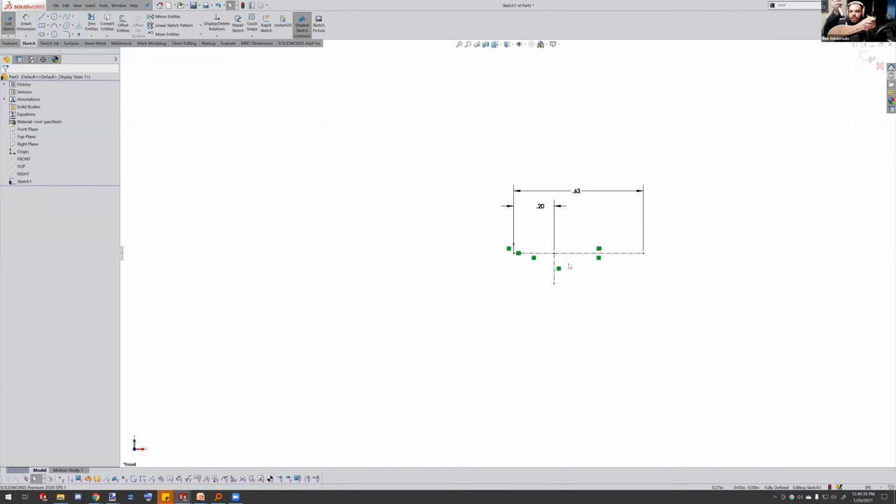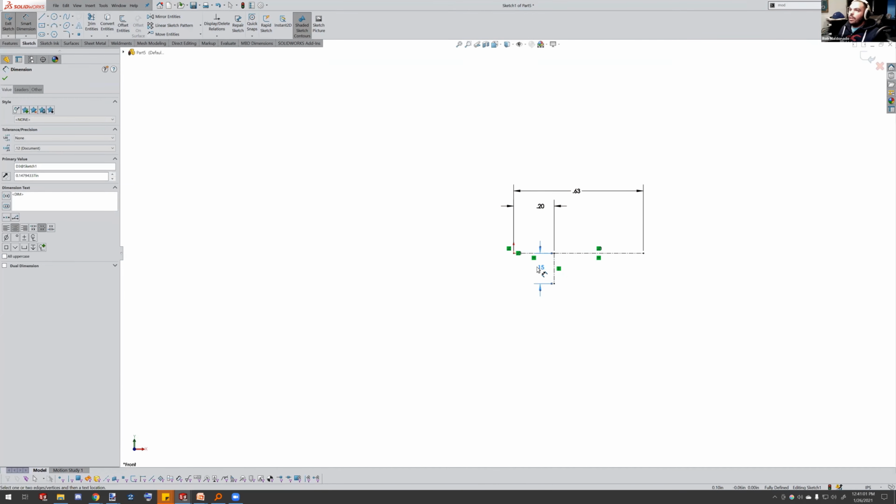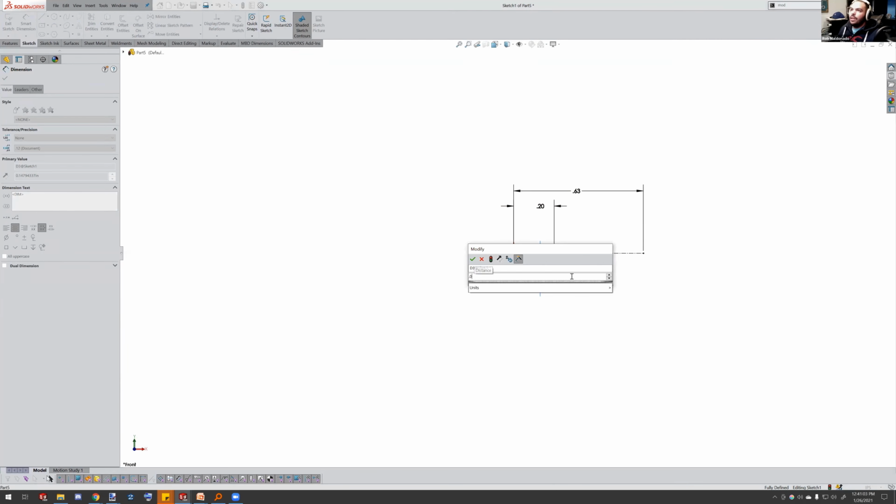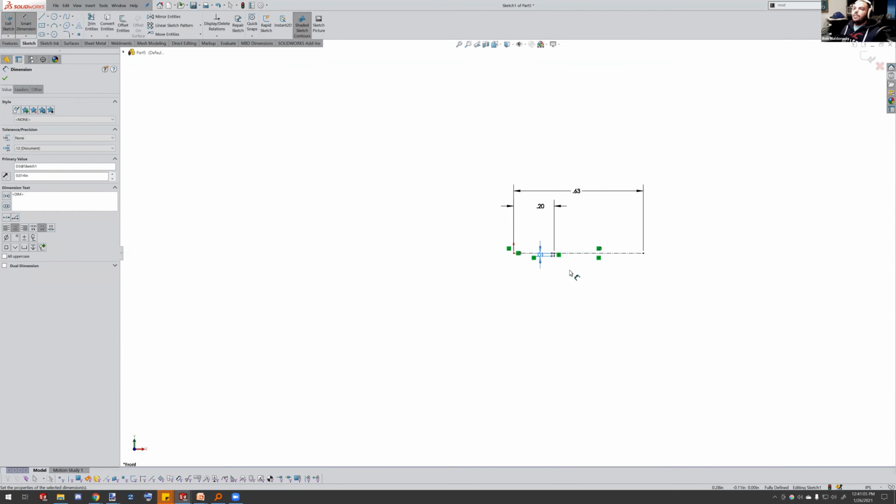So let's say I take my calipers and I put it up against the surface like this, and I'm reading 14 thousandths. Of course, it's not the best example because the curvature is constantly changing, but pretending that this is a cylinder, it's just generally the technique. Let's say I reach a reading of 14 thousandths. So I can put that dimension and put 0.014 for 14 thousandths.